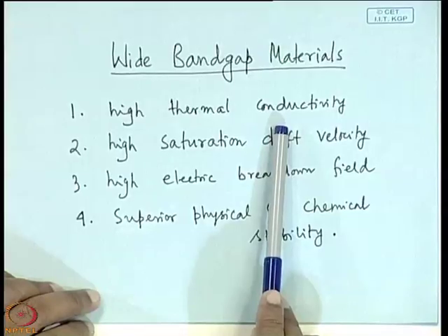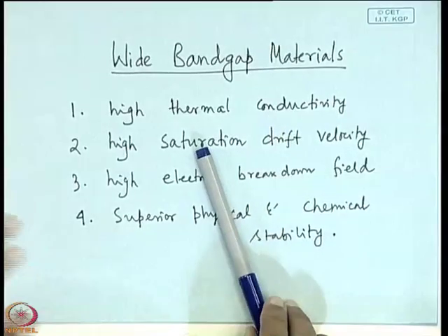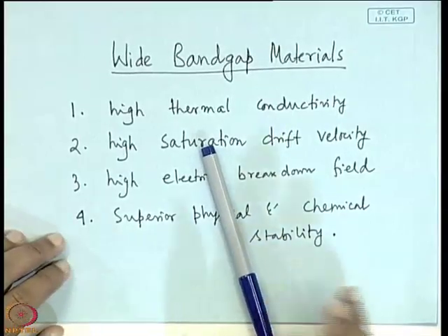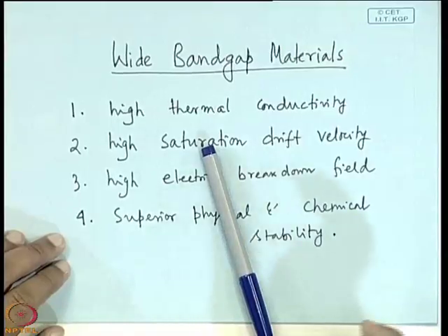Heat dissipation, right. So for particularly high power applications, like a high power transistor, or a thyristor type of application where high current is involved, the circuit basically is heated. Then there is a heat sink. Metallic heat sinks are there. Generally aluminum or copper is used.